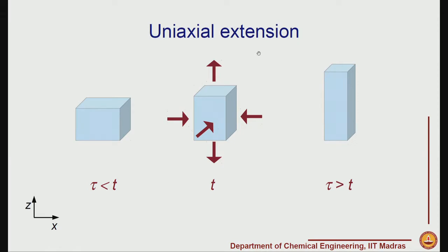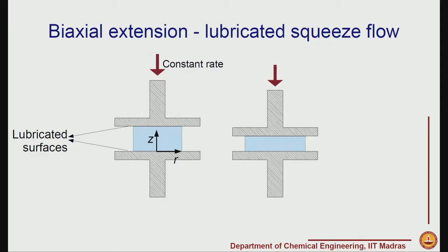because in case of fluid-like material the basis will always be the present state, because there is no such thing as a uniquely determined stress free state. So, there are multiple options, and we might as well use the present state, which is a well defined state. So, this is something which cannot be achieved so easily, but again using a rotational rheometer